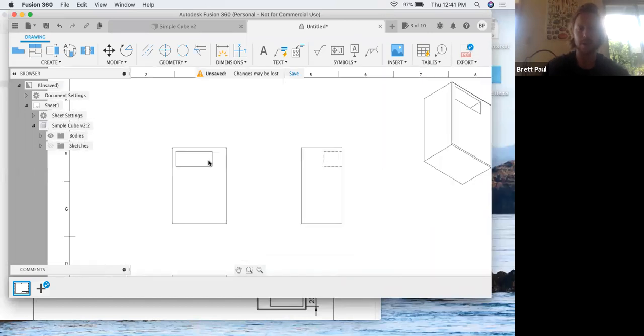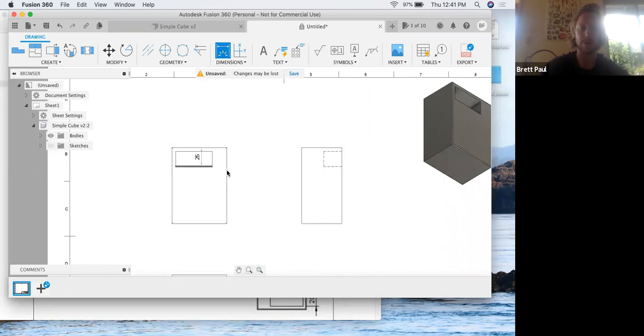So to do that with this part, let's just go ahead and start. We've got a width to this thing, a height to this thing, and this view here is rotating it. Oh, you highlighted the wrong thing. I'm using dimension up here, and I believe you can just click D. So I exited that function. You can just click D, and dimension is highlighted. Okay, and we've got our